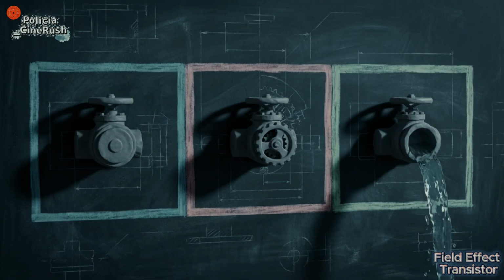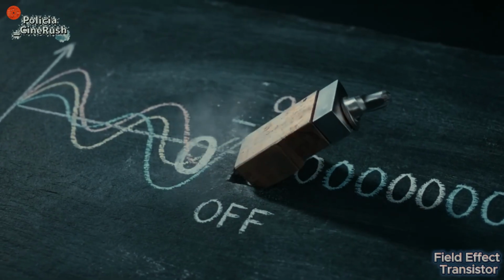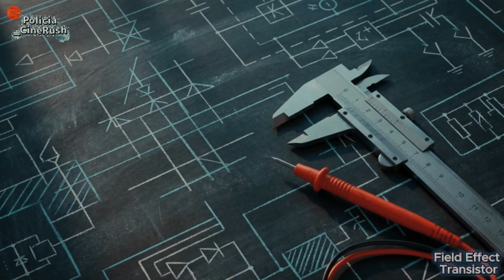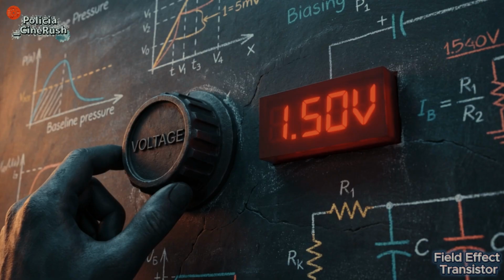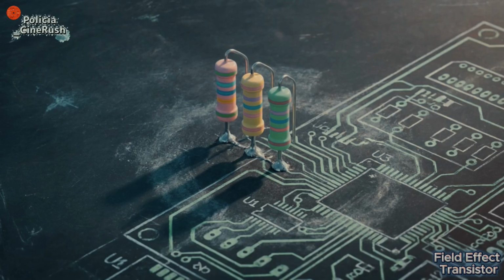By shifting smoothly between cutoff, the ohmic region, and saturation, a single microscopic component can function as both a highly precise volume dial and a strict binary switch. To make sure a FET rests exactly in the state a circuit needs, engineers use a technique called biasing. Biasing is the practice of applying steady baseline voltages to set the default resting pressure of the gate. Depending on the design, you might see a fixed bias, a self-bias, or a voltage divider bias. These are just different physical arrangements of resistors used to dial in that exact resting voltage.